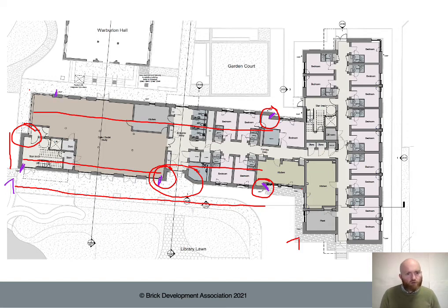Making sure that the bracket is correct. And then if we need another one here, it looks like we could put one there, and then hopefully this dimension here is within the 12 meters. This next panel looks okay, and then we just check whether this section here is within 6 meters. There's a couple of rainwater pipes in there, so actually maybe we can put one in here.